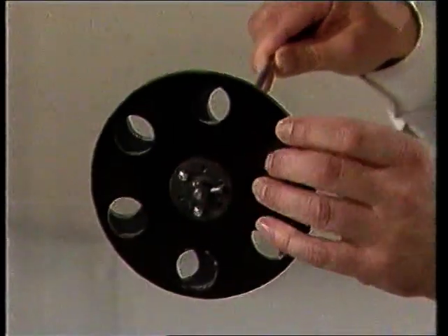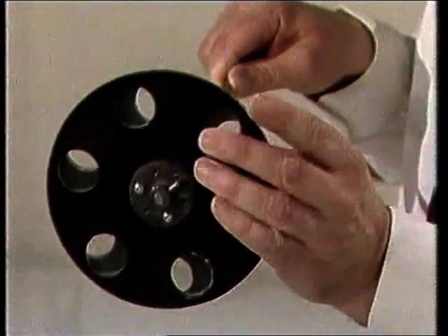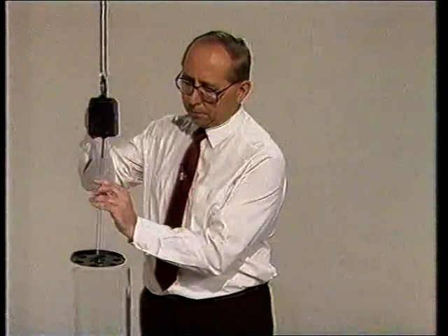The missing factor in our theoretical model is damping. So we must include in the model not only the restoring force and the mass, but also the damping force. This system here was quite lightly damped. So to see the effect more clearly, I'm going to put a physical damper onto it. This is simply a plunger which can move up and down in a tube. And I can vary the damping effect by changing the size of the holes at the bottom. I'll attach it to the mass.